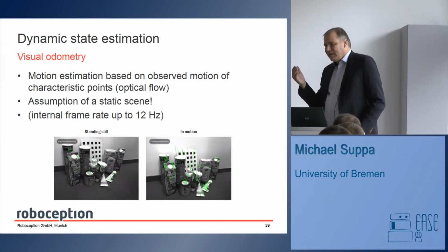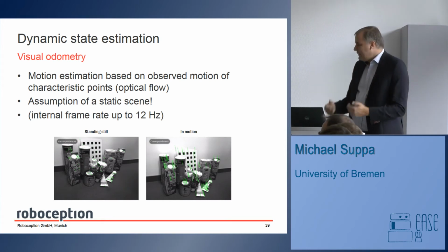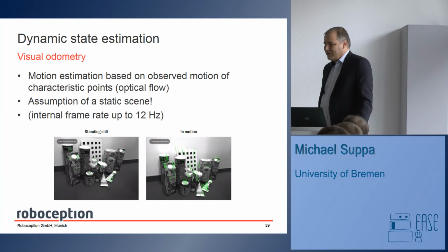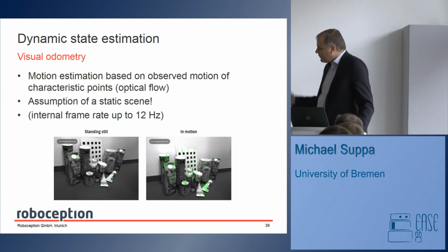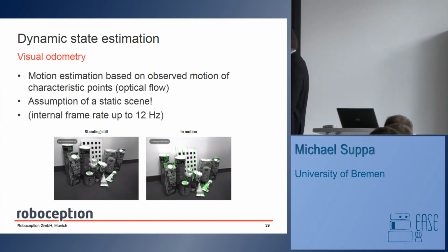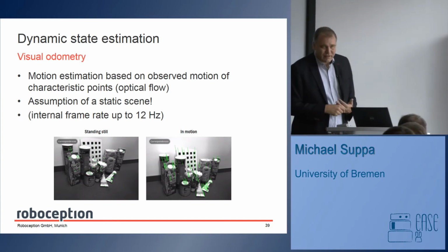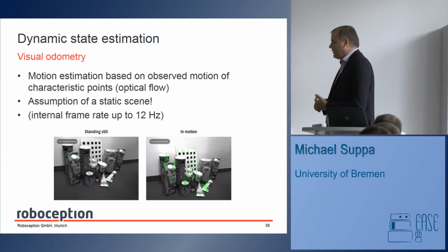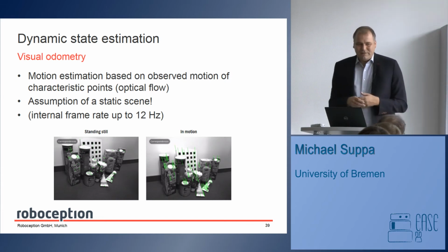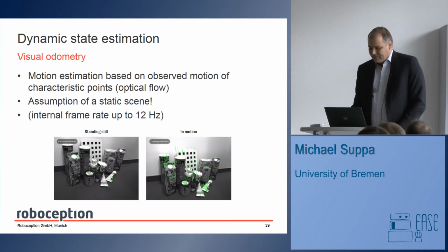In addition to that, we are talking about stereo odometry. We have the depths, which means that we can compute the motion directly. You can do the same with a mono camera, but then you have the problem that you don't have scale. In that case, you either need some pattern you know, or an initial movement you know, in order to estimate the pose correctly. By using a stereo system, that problem is taken out because you know the depths of each feature.